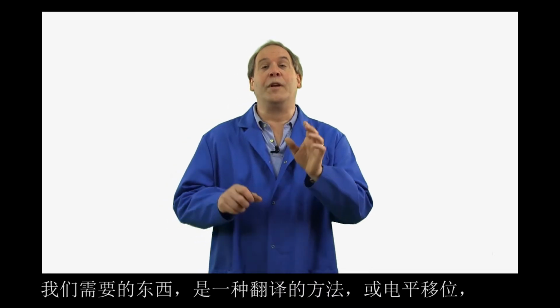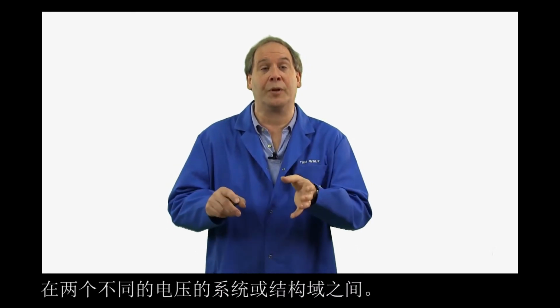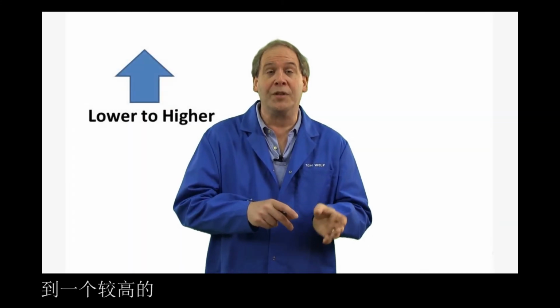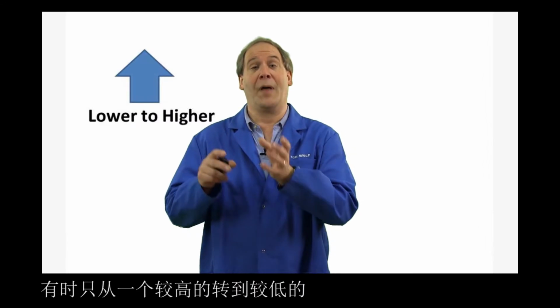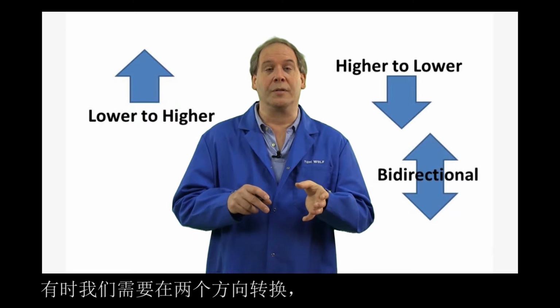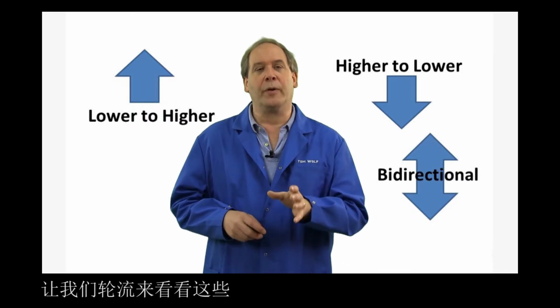What we need then is a way to translate or level shift between two different voltage systems or domains. Now sometimes we only need to shift from a lower voltage domain to a higher one. Sometimes only from the higher domain to the lower one. But sometimes we need to convert both directions, depending on which way the signal happens to be going. Let's look at each one of those in turn.